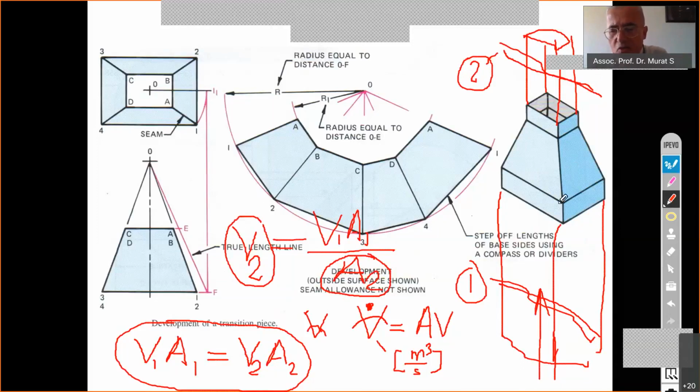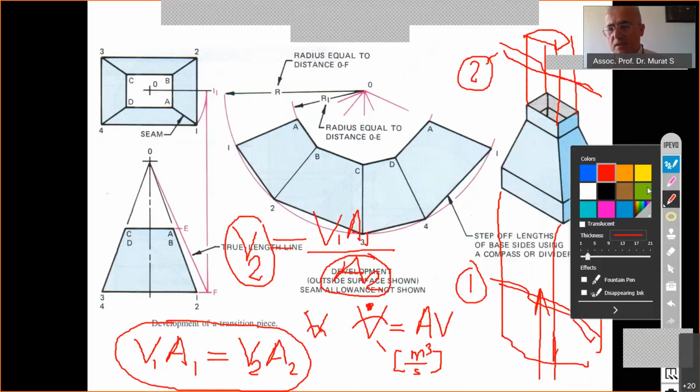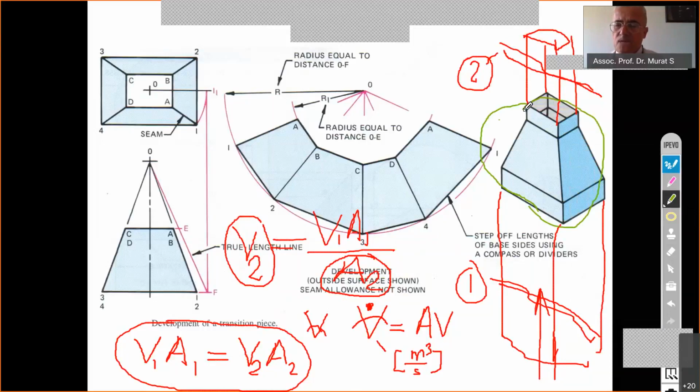Well, the question is, to be able to connect a larger channel and a smaller channel, obviously we need an adapter, a transition part. Such a part is needed. It is by definition a loft, but here, since the work is sheet metal, this loft is a sheet metal component. Which figure is to be drafted over a flat sheet such that after folding we have the adapter in the correct size and correct shape? The answer for this loft is over here. Development.